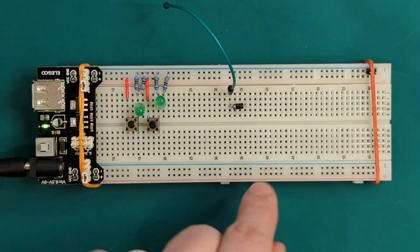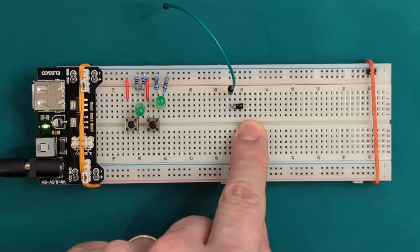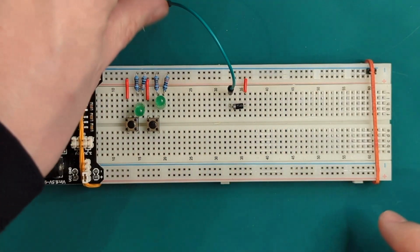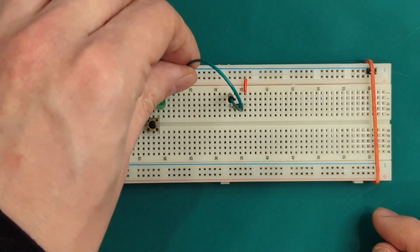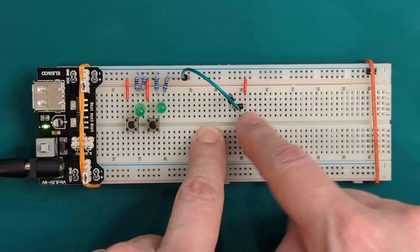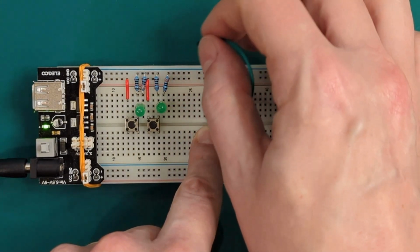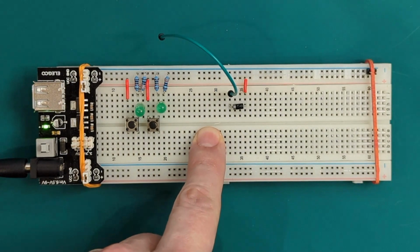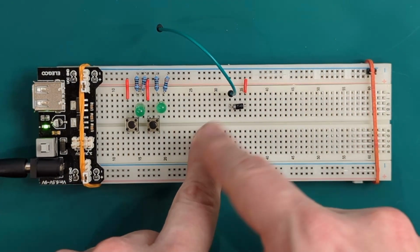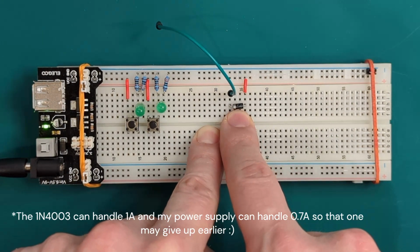So let's put the positive side of the diode, it's usually called the anode, to 5 volts. If I do this and I connect this input to a high level, then there will be no current flowing because both sides of the diode are actually the same voltage, both are 5 volts. If I connect this to a low level, and I won't do it, current will actually flow directly from 5 volts to 0 volts, shorting this circuit and sending lots of current through this diode and probably burning it up.